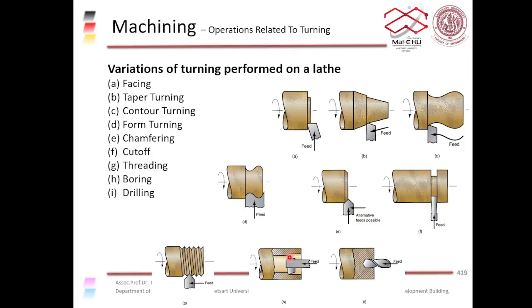Next, they start to produce a long rod, and then they use a bulk forming process, like rolling, to produce a thin, long rod, which is stronger because of the cold working. Right, with cold working you have work hardening. And then they start to cut a hole inside.